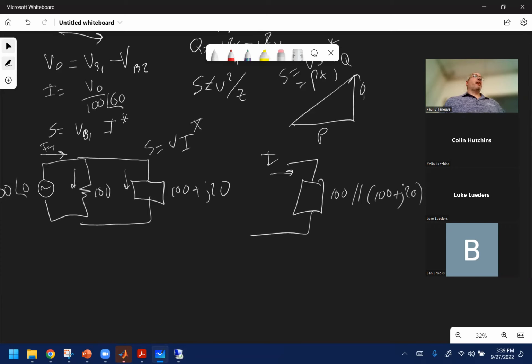Okay. Once you do that, draw the power triangle. And then the third step is to find the capacitance of the capacitor connected across the load. I was really looking for a farad value, but if you gave me an X sub C, that was fine. When I did my power triangle here, it kind of looked like this. This angle here was pretty low. Let's just say it's 4 degrees. The cosine of that equals what? I don't know exactly, but I know it's greater than 0.8.